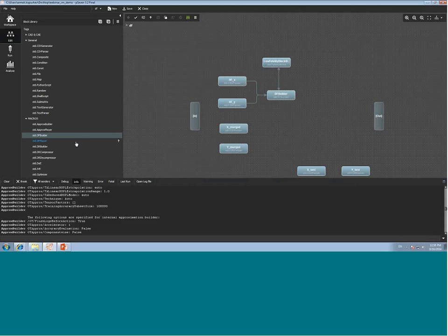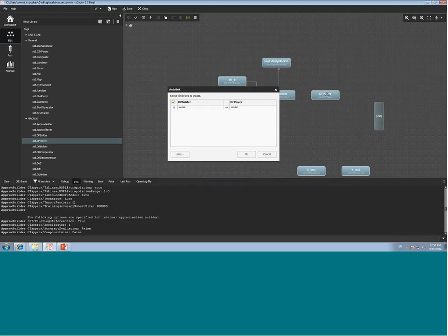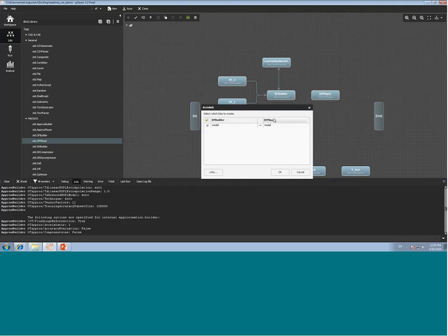Okay, now let's add the data fusion player. This block will perform predictions of the data fusion surrogate model, so make a connection from the data fusion builder to the data fusion player.